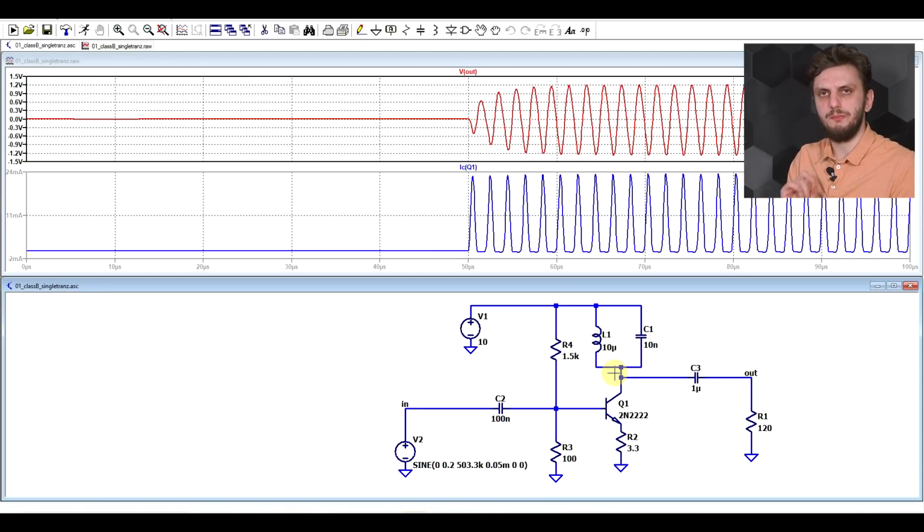Well, there's one really important aspect here to consider. This sort of amplifier has an output signal proportional to the input signal. So even though the amplifier amplifies half of the input signal, it does amplify it in a linear proportional way in reference to what's on the input, and then the other half of the signal, the unamplified half, is provided by the LC circuit, which will provide the mirror image of the initial signal.